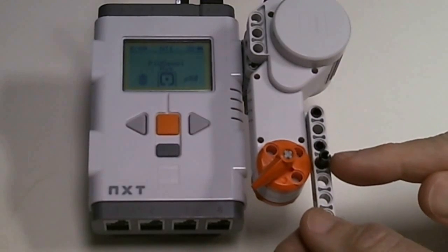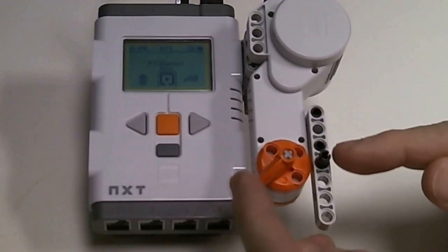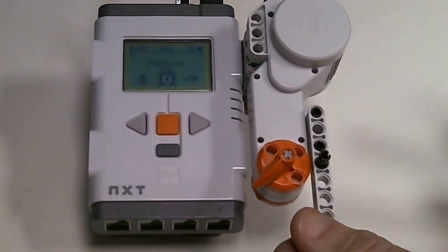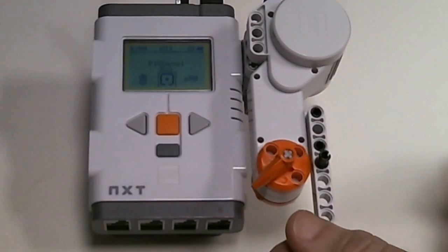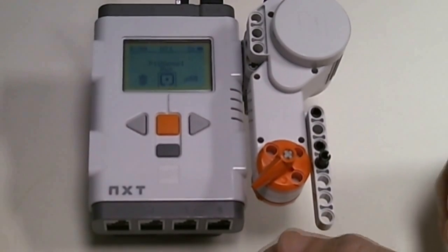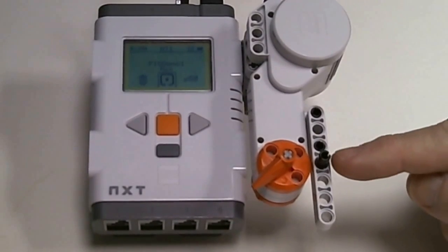What I'm doing here is I've put in a mechanical limit. Now I'm just using a pin that this pointer hits. Your arm itself might reach a mechanical limit if you're doing this with a robotic arm, or you might have the gripper go all the way closed or all the way open for that reference. So there are different ways of establishing the reference.